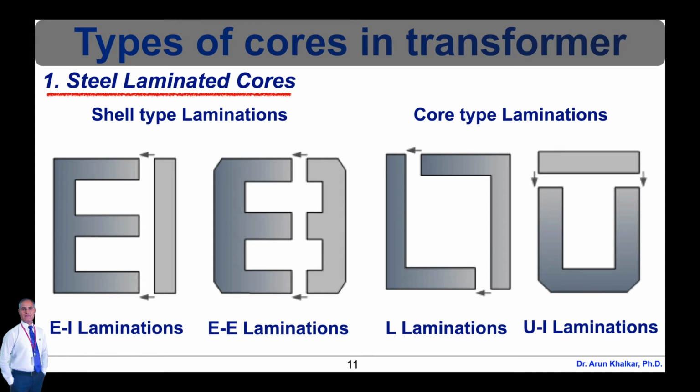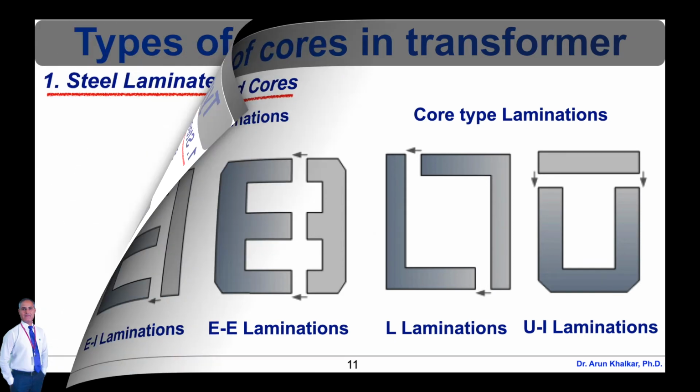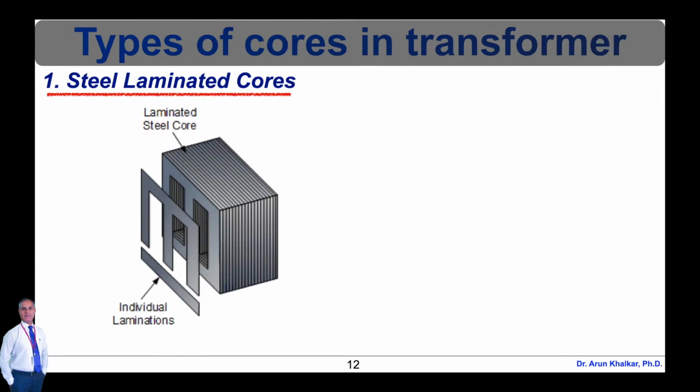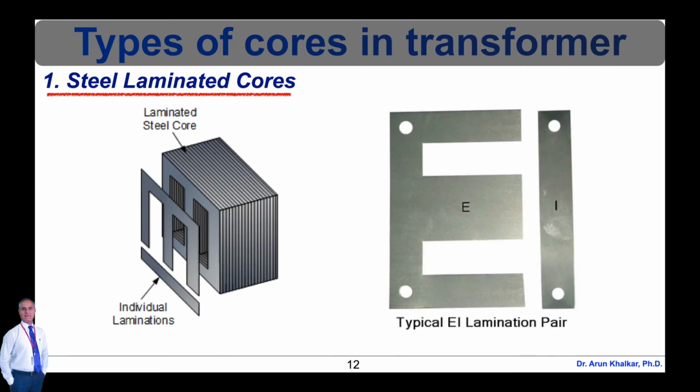EI core laminated transformer construction is mostly used in isolation transformers, step up and step down transformers, as well as auto transformers. One common design of laminated core is made from an interleaved stack of E-shaped steel sheets capped with I-shaped pieces, leading to its name of EI transformer. Such a design tends to exhibit more losses, but it is very economical to manufacture.